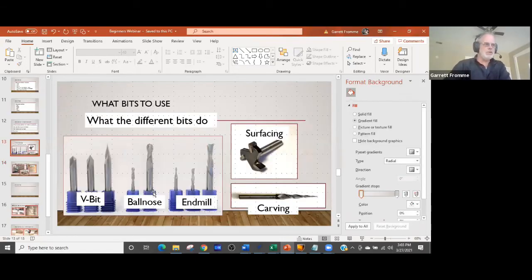But that's generally what the ball nose is for. It's just to add accent to your projects or to soften up corners. You can use a ball nose in the lettering so long as your letters are going to allow for the size text that you're working with. Since everybody's V-carve users here, you'll know that when you generate your tool paths to see what it looks like.